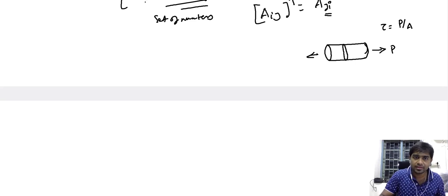Now on the other hand, when you consider a sample that is made up of metals or an alloy, it means we have a rather regular arrangement of the atoms, and when we have a long range regular arrangement of atoms, it is possible for us to describe definite planes using Miller indices. This could be a specific plane.